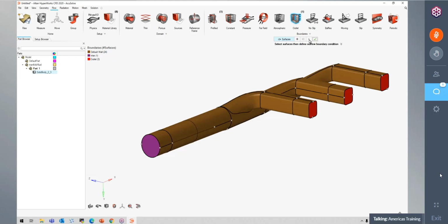If you press that little triangle, you'll be able to create more of the same tool that you're using. So if you have different inlets with different boundary conditions, you'll select the surface and then you click the little play button here, and it'll jump to the next thing so that you can create another one right after. When you click the check mark, that finalizes everything. It closes the tool, and then you're done. So that's the main difference between these two here.